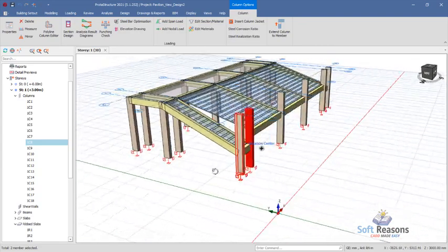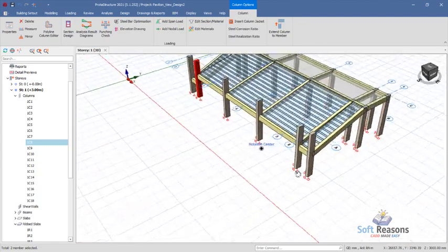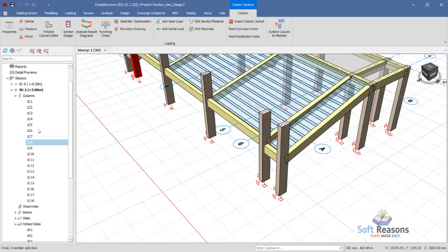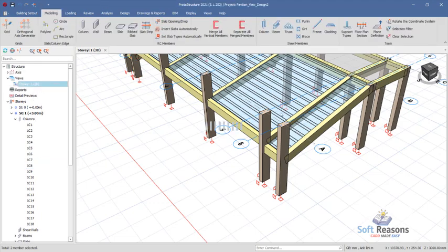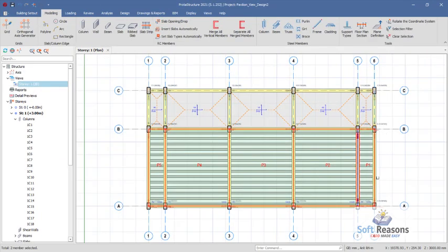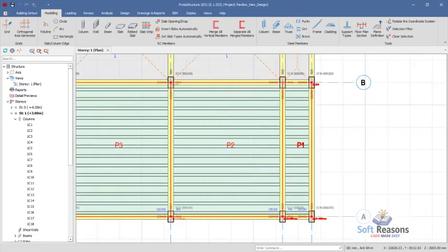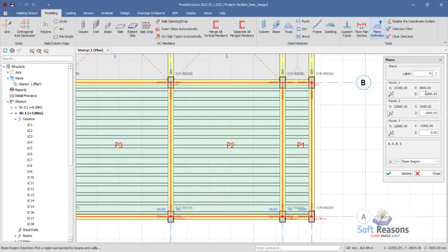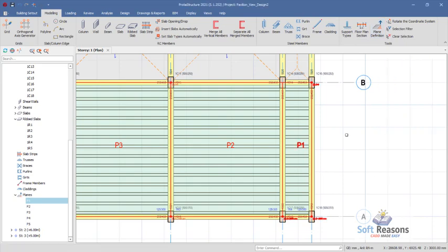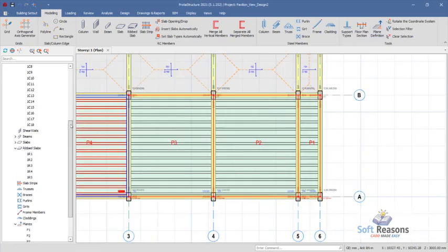Okay, so having done that, in that provision we come over to this other provision, navigate to the plan view P1. We also select this plane, make sure this plane is selected, right click, hit properties, and then change it here to 2400. Come over to these provisions and also 2400. Okay, so click on the update options and then close options, get to 3D again.